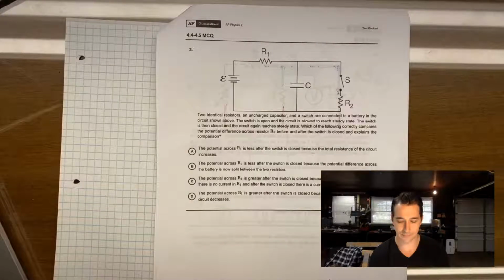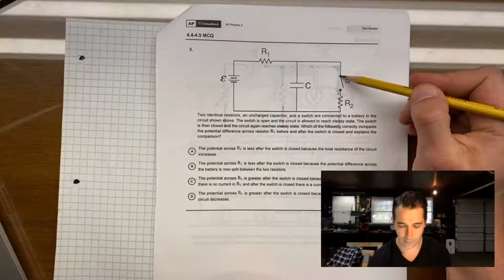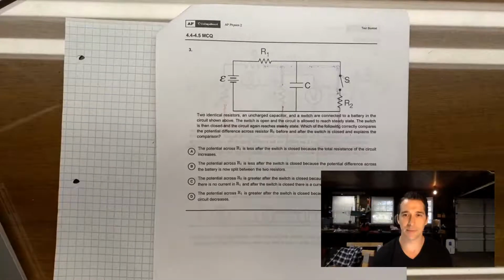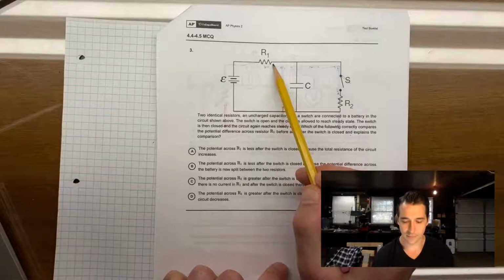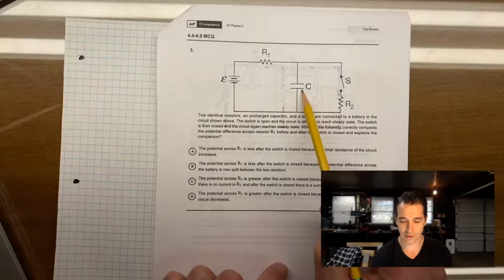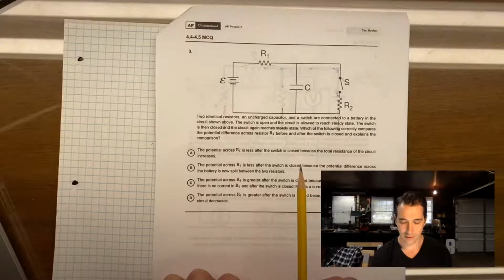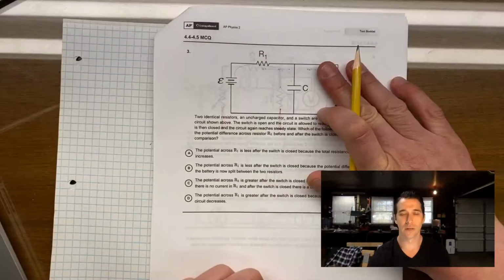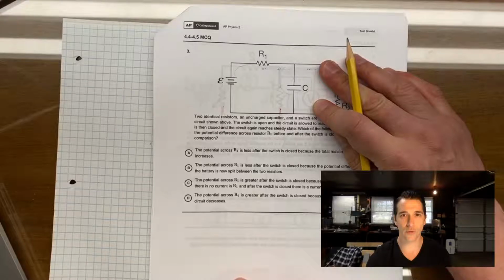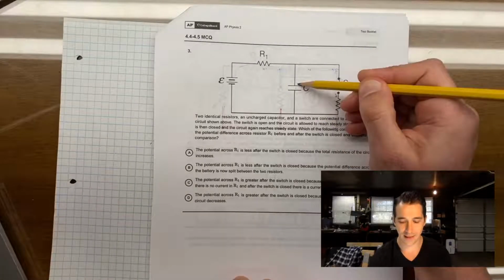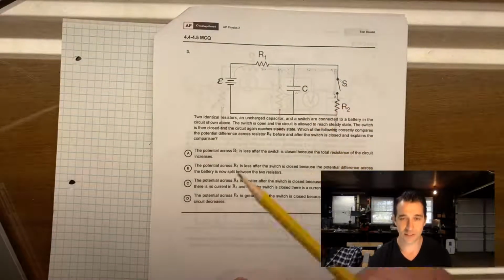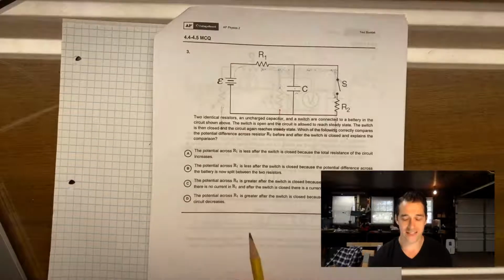think about this. Switch is open. All right, well, if we first plug in our battery, what would happen? Current flow starts charging up the capacitor. Okay, that makes sense. Then the capacitor is fully charged. What did we say? This part of the circuit's completely out. What did we say when a capacitor is fully charged? This gap does not allow electrons to jump from the negative side to the positive side. They can't bridge that gap, which means once fully charged, R1 has no current at all.